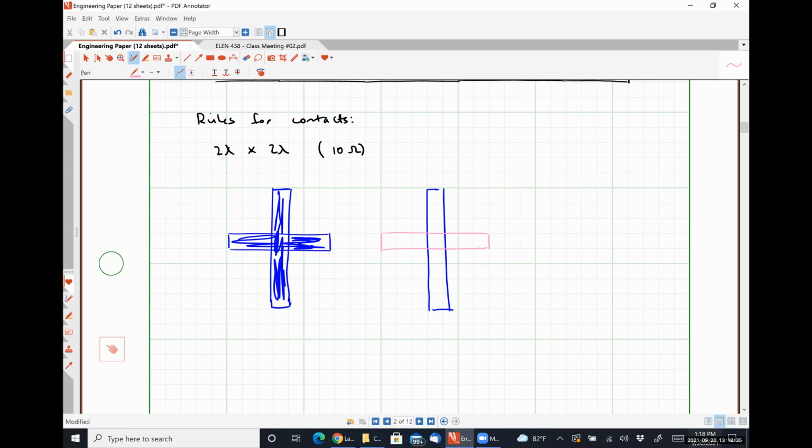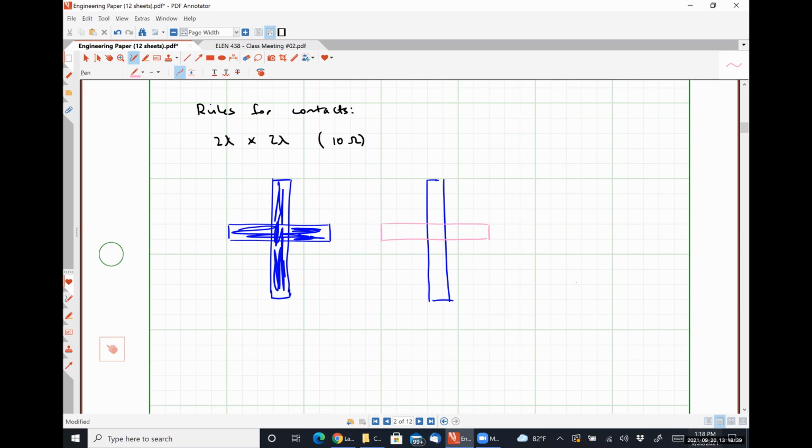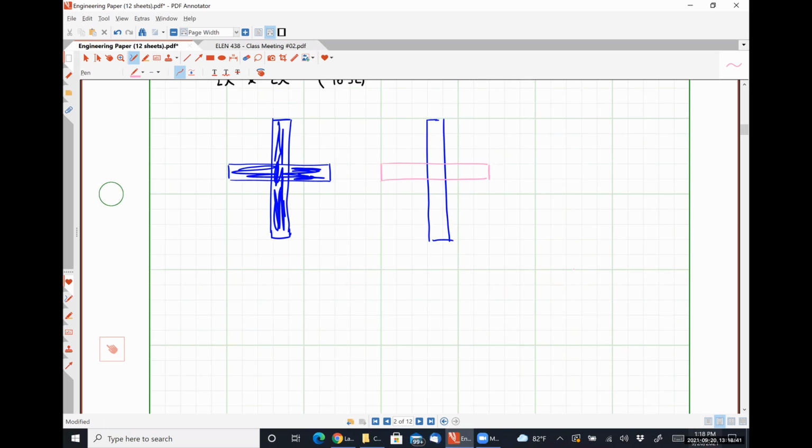There is one specific portion of the metal layer that is the only part of a CMOS process that does not have a lambda-based or scalable design rule. That's a bonding pad. All right, so let's start talking about specifics of the metal layers.